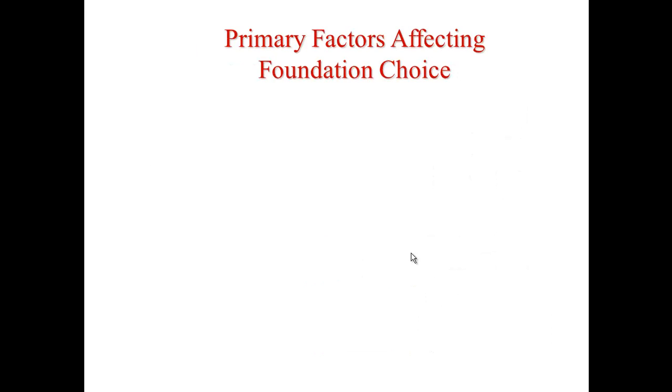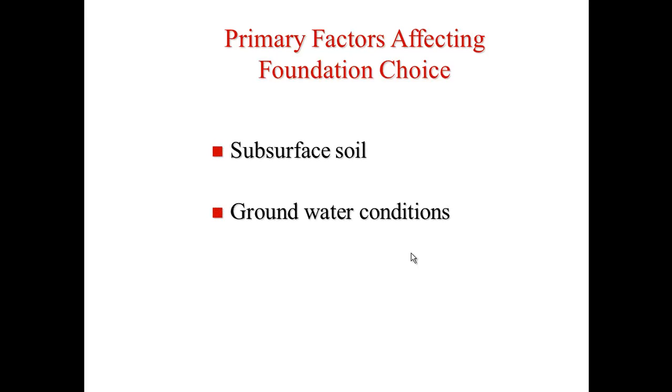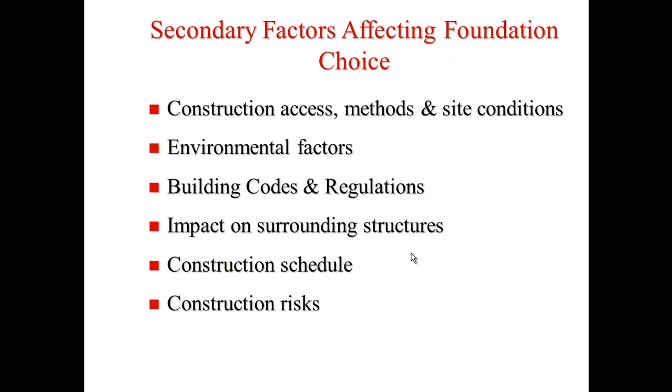Primary factors affecting foundation choice: subsurface soil, groundwater conditions, structural requirements. Secondary factors: construction access methods, how easy is it to get to the site; environmental factors, am I going to be draining some wetland; building codes and regulations, impact on surrounding structures, construction schedule, and construction risks.